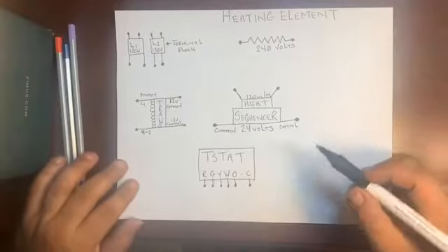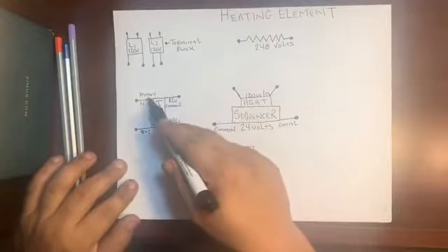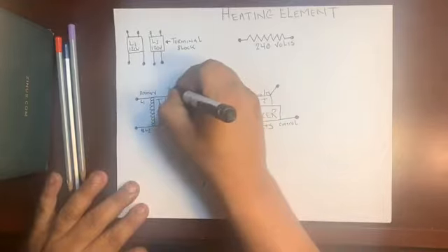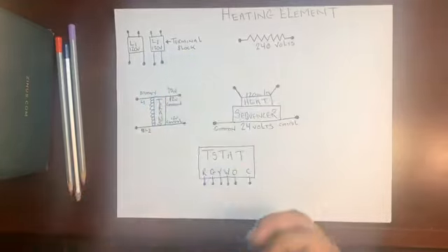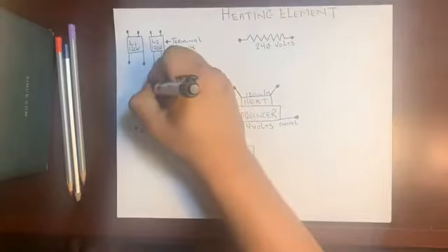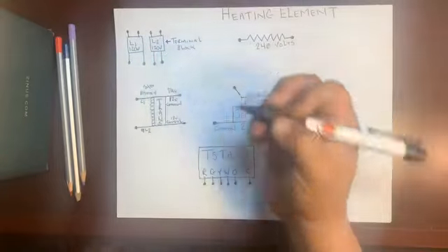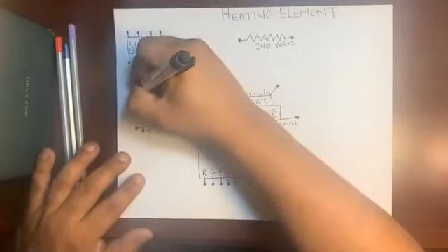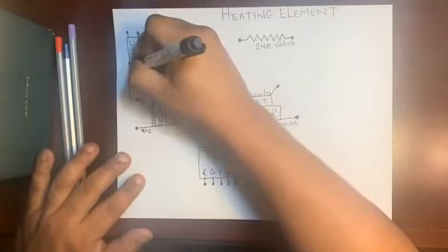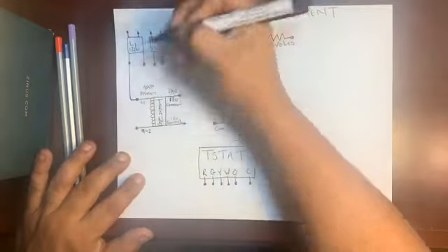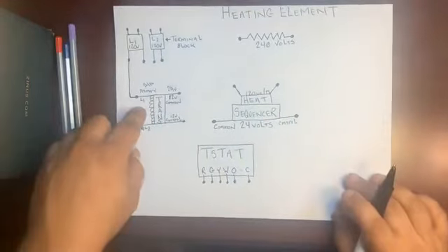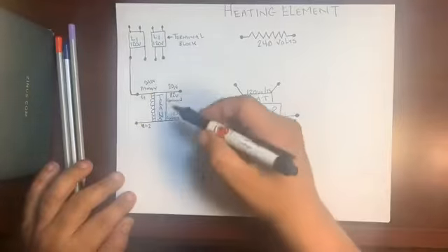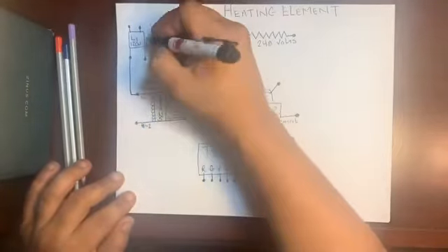So let's go ahead and start with getting 240 volts to the primary side of our transformer, because that's how we get the 24 volts that we are seeking. But our primary needs 240 volts. So let's do that. L1, L1. Let's go over, bring our line, connect. 120 volts. Transformer says, hey, I'm halfway there, I need 240. So let's bring L2 to L2.